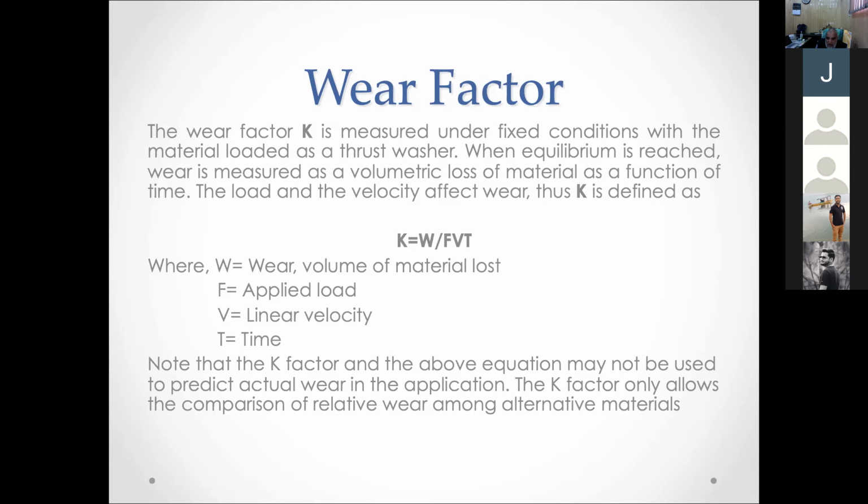Note that the K factor and the above equation may not be used to predict the actual wear in the application. The K factor only allows the comparison of relative wear among the alternative materials. Because wear can change at the operating stage, you cannot exactly get the value of the plain bearing life based on this. At the operational stage, some conditions may change and the wear capability of that bearing material may reduce drastically, or it may have higher values also if the conditions are favorable for wear.